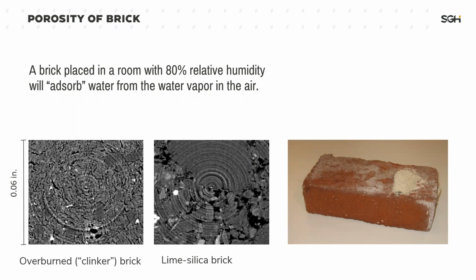And if you put that brick outside in the cold and it drops below freezing, all those tiny water droplets will freeze and expand. And we generally say that if more than 80% of the pores in the brick are full of water, so if it's over 80% saturated, then we would expect there to be damage if the brick were to freeze and then thaw. And that's what we refer to as freeze-thaw damage.